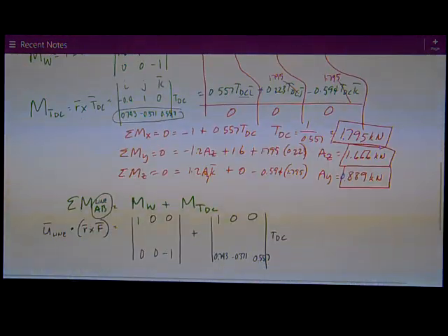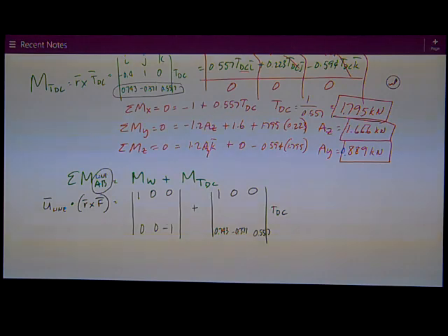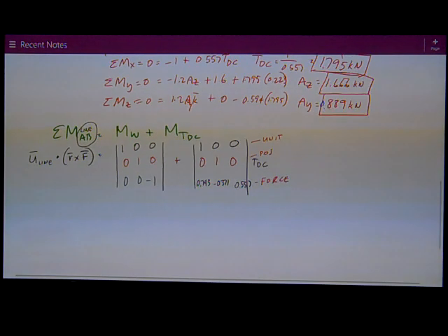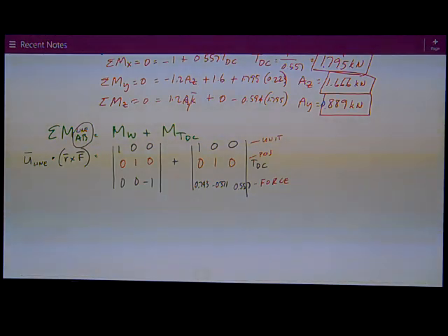So this middle row, the position vector, just looks like 0, 1, and 0. Same one for the force in the cable, 0, 1, and 0. Remember that from the equation sheet, the top row is the unit vector and its components, the middle row is position, and the bottom row is the force. I have a whole lot of zeros in these determinants, so that really helps me.